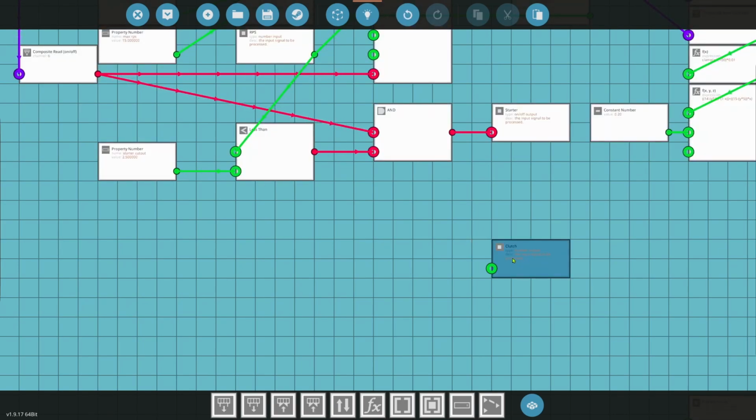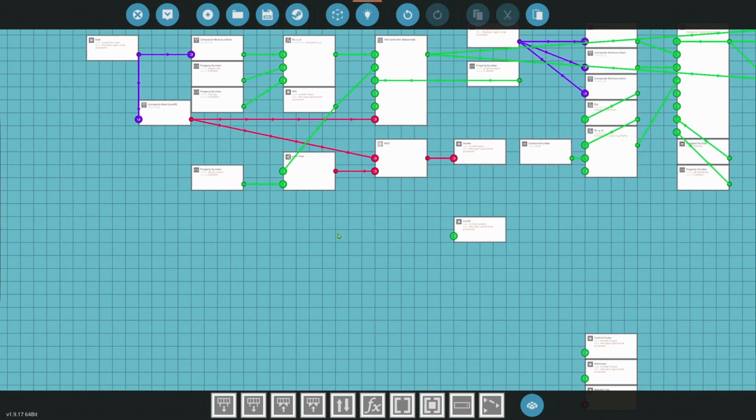It takes in a lot of conditions. For example, there are conditions IRL. Let's say you have a really heavy trailer on a tractor trailer and you're going up a hill. You're going to have to rev up higher and you're going to have to feather the clutch. That's you putting the clutch pedal in and out to make sure you don't stall the truck. And so this will automatically do all of that for you. It's a pretty simple system here. So we're going to take our clutch and I'm going to get working on this.